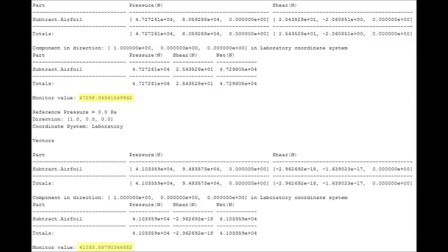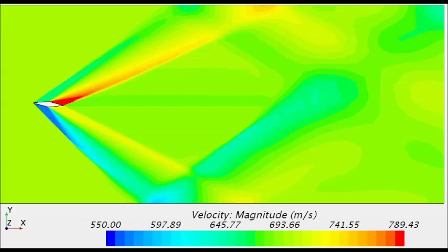It should be noted that the two airfoils were drawn to be of similar thickness and chord length. These simulations help show why we use high-speed airfoils at high Mach numbers, but further subsonic simulations could show how they do not perform well in such low Mach regions.